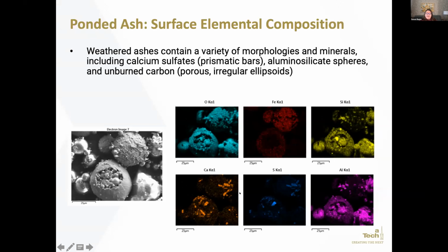We can overlay these two images here, and we can see where we're getting gypsum precipitated in these products. And that's part of those cementing bonds that we saw in the previous images themselves. I mentioned earlier that we have iron deposits usually in fly ash as well, usually a reasonable concentration of iron. And that's what you see in the red map here.